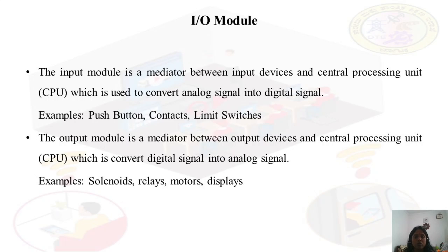In the I/O module, we will be using the electric isolation and signal conditioning. For electric isolation, we will be using the opto isolator or opto coupler, because the CPU cannot handle much voltage. The CPU can handle only the range from minus 5 volt to plus 5 volt. Understood? What is opto-isolator, what is optocoupler and all, we will see in the coming sessions.